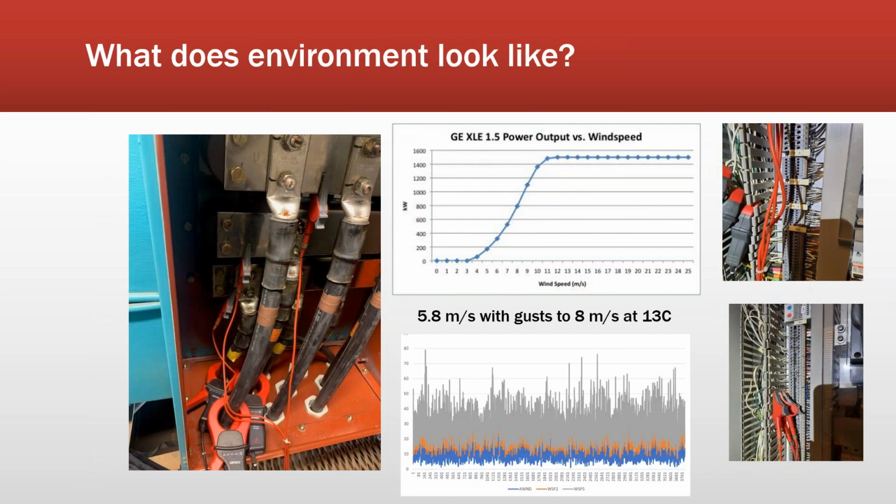For that site, some of the towers, for whatever reason, somebody decided that we wanted to test up tower. Part of the benefit of this technology is if the controls are down tower, I don't need to climb. And if you ever meet me, you'll understand I'm not into cardio. So we clipped on now, because I'm only clipping on around one conductor of each phase, that's just a CT ratio of 3 to 1.